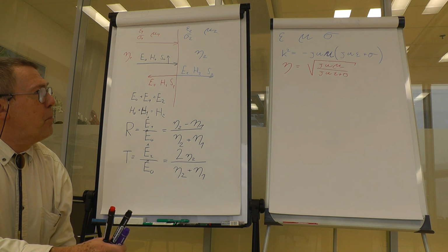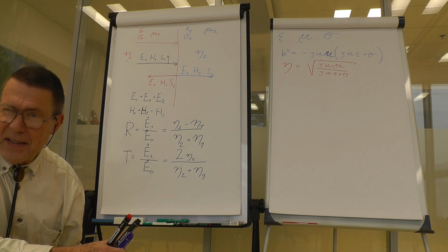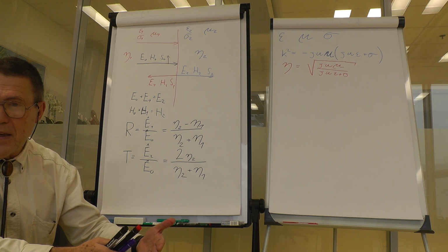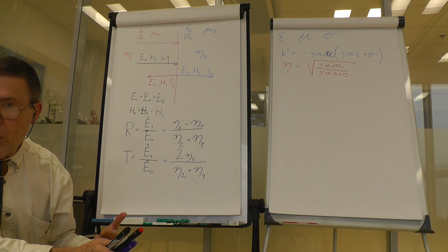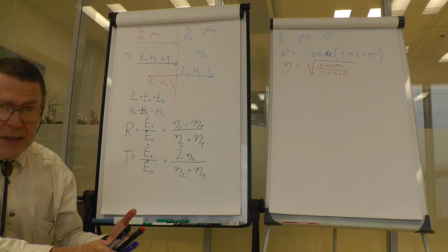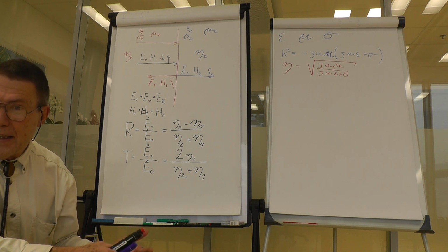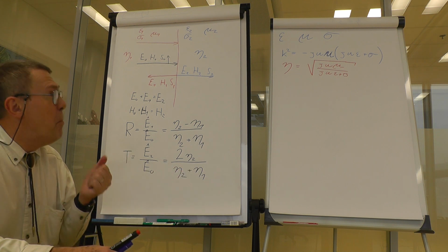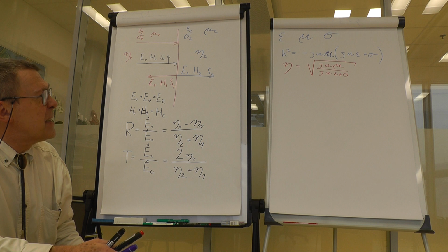Now, conductivity at DC means that there is a charge transport through the material, and we can measure a ratio between current and voltage, and given we know the shape of the sample, we can then establish conductivity or specific conductivity. But at high frequencies this is impossible.